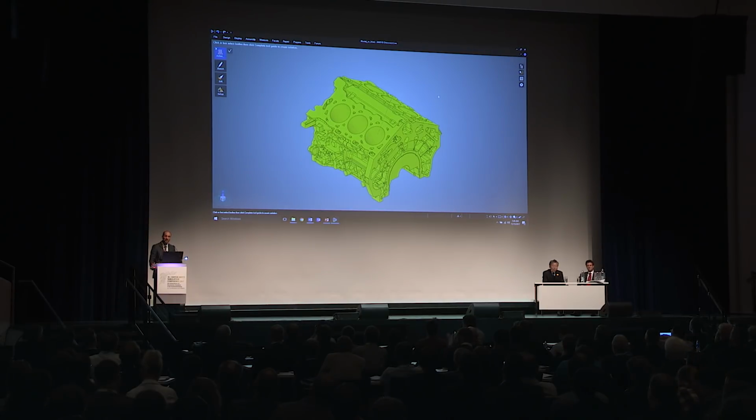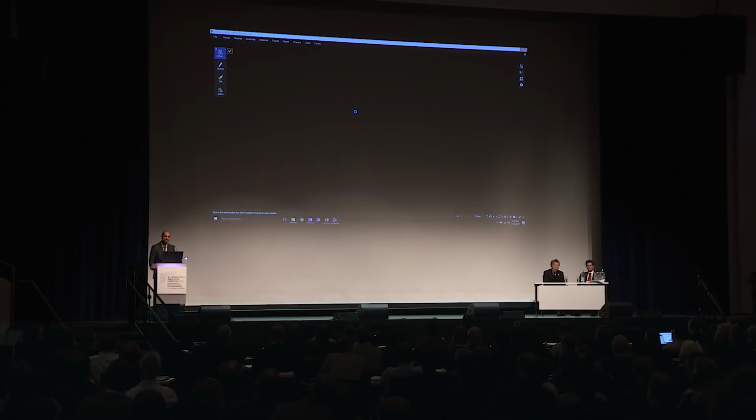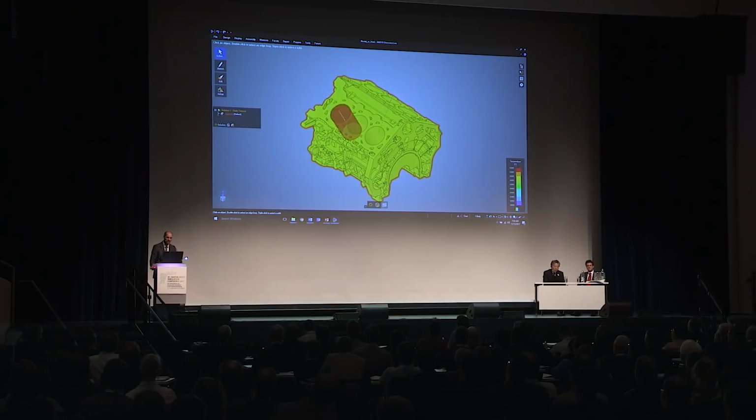Now, where should we apply a boundary condition? I think that probably these cylinders that appear here in the middle are a good place to apply an amount of heat. It's going to be generated. We know combustion's going on there. It's really going to generate a lot of heat. So we'll let this open up. We'll give it 2 more seconds. We do think it will run. If not, we may move on to another one at the same time.